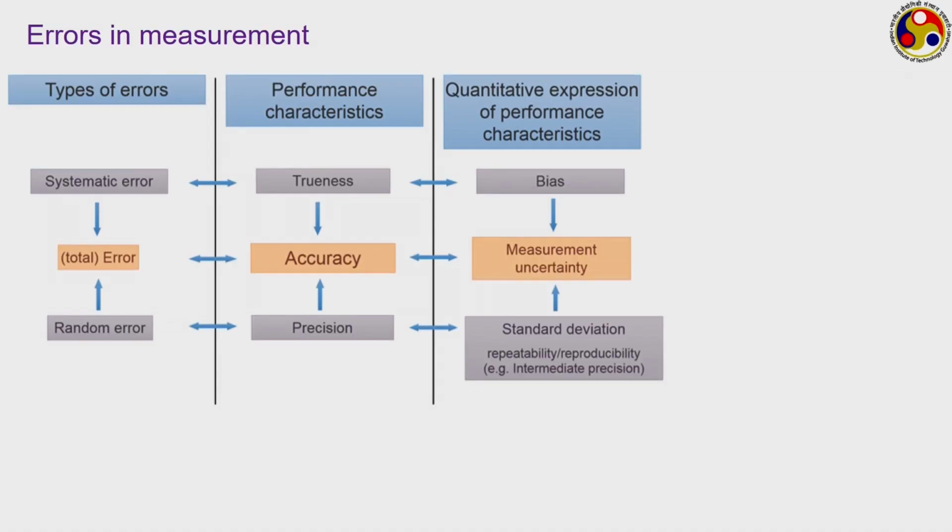Like we have discussed in the previous lecture, there are 2 broad kinds of errors that we may find in measurement. One is systematic error, which generally is associated with very common terms like zero bias error, zero drift, sensitivity drift, etc. Measurement errors can be quantified. We can easily identify their source, and therefore, via the process of calibration, we generally can eradicate or at least minimize the amount of systematic error from a final measurement.